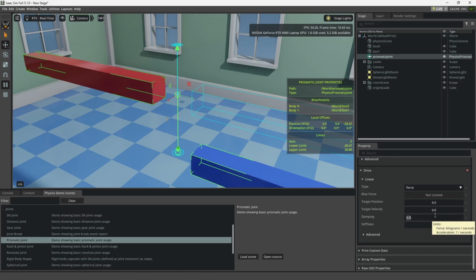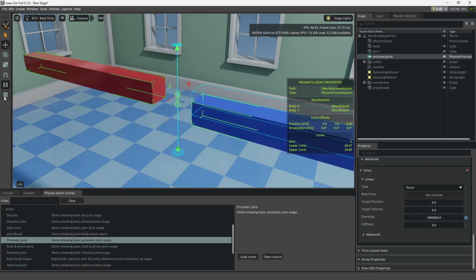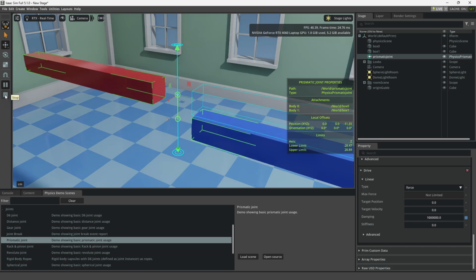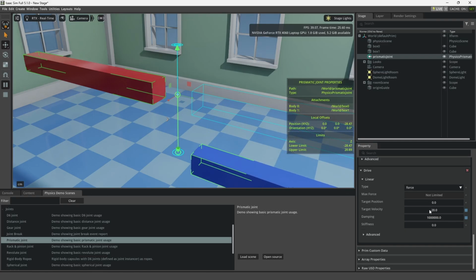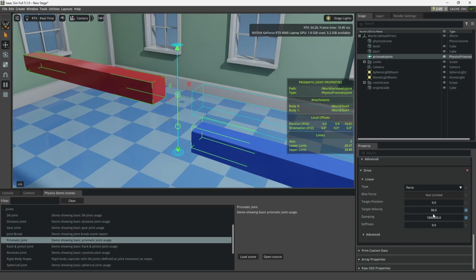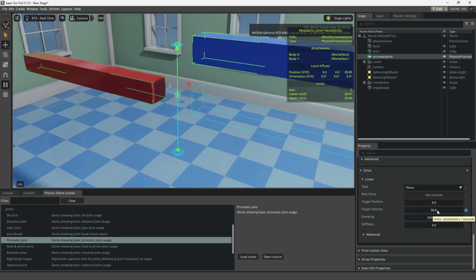And that's because we don't have any dampening or anything. If we were to put the dampening on like we had, make sure that number is extensive, then it slowly drops. If we were to put the velocity to a negative amount, like -20, hit play, maybe that's not enough velocity, and maybe I'm not heading in the right direction. Maybe I need to make it 50. There we go. 50 actually brings it up, so a positive number brings it up.